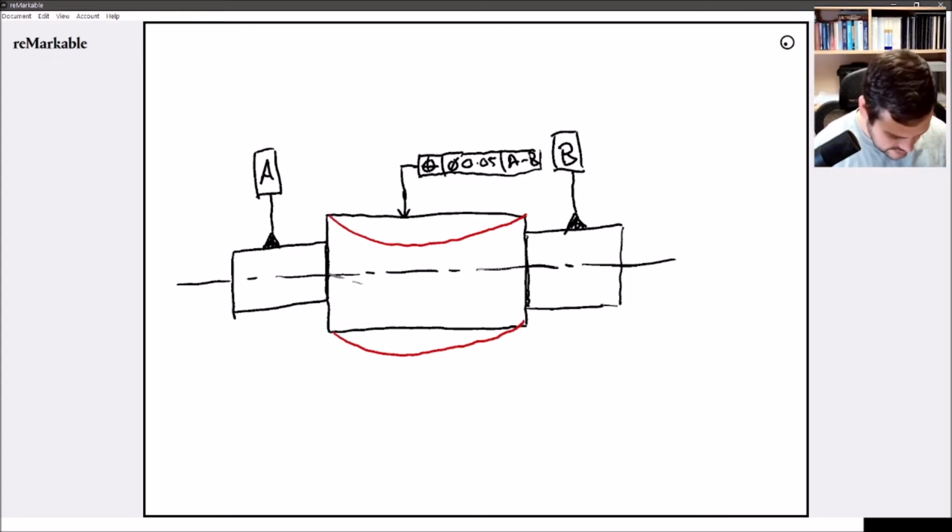So if we consider our center line running through something like that, effectively what it's saying at its worst point, the dimension between there where I've got my little question mark, the biggest that can be from the stipulated geometric tolerance that we've specified is diameter 0.05. And that's in reference to either end, where we've referenced those datum planes of A and B.